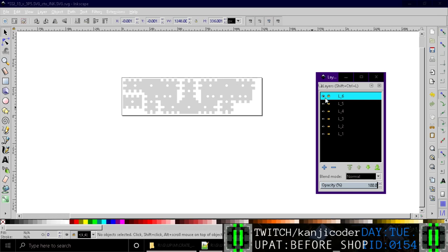However, after 80% speed, if you try something like 100% speed, I think the servos or the gears or something slightly slip and you get slight inaccuracies. So you don't actually want to go that fast. Also, there's a lot of shaking when you go that fast. So 80% speed is usually what I choose. It's about as fast as I can go without losing quality of the path.